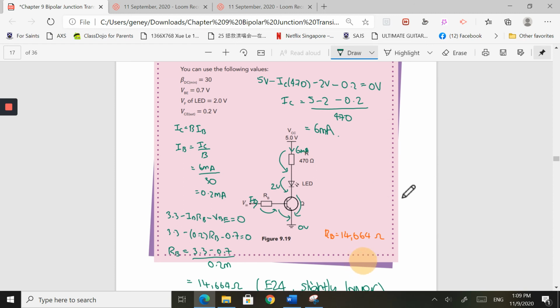So just to summarize, this transistor works as a switch. I have a voltage here. That means current is going to flow into the base, and once I have a small little current flowing into the base, boom, it opens the floodgates for all the current to flow through the collector and down through the emitter. Along the way, as it's flowing, it's going to turn on the LED. That's why it acts as a switch, turning on the LED here.